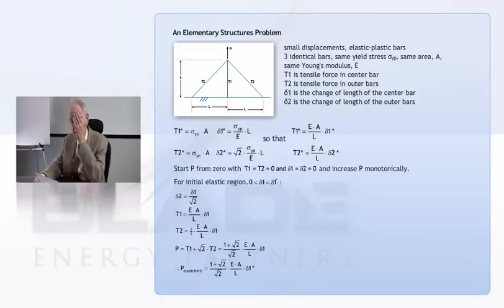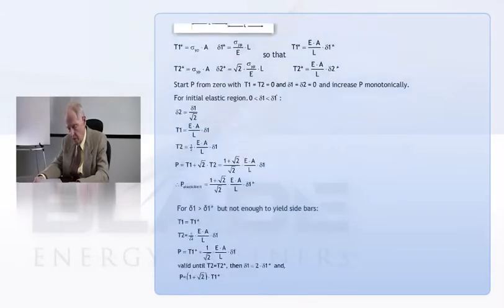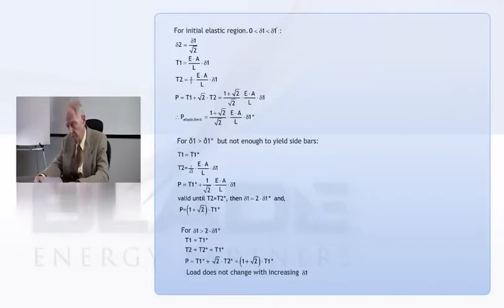Now these bars are elastic, perfectly plastic. So they go up, they yield, and the load stays constant, unless I reverse the load. And with a bar like that, if I pull, starting with 0 stress, I go up to the yield point, and then if I decide to compress it and yield it the other way, I've got to go twice as far. I've got to remove the stress I've already put on, and then I've got to go re-yield it.